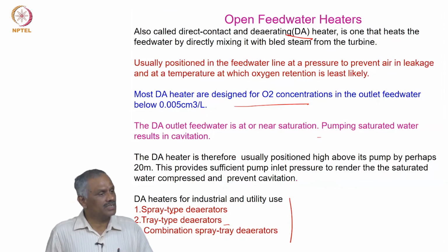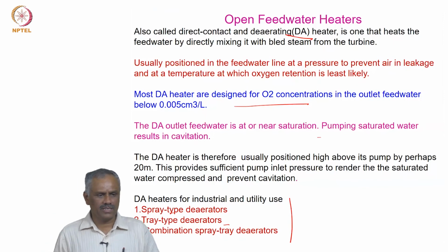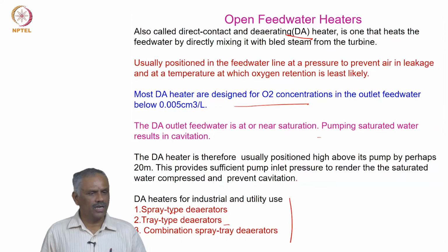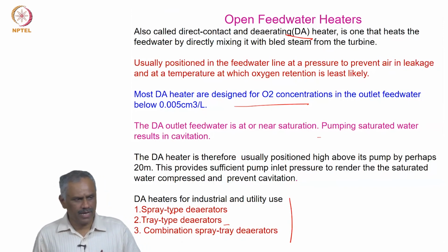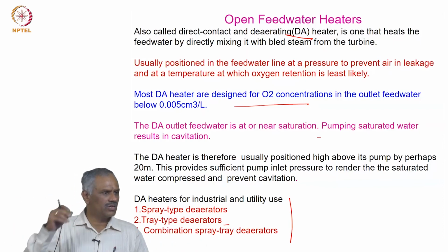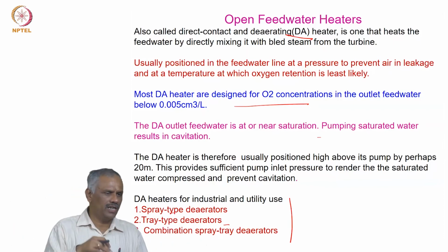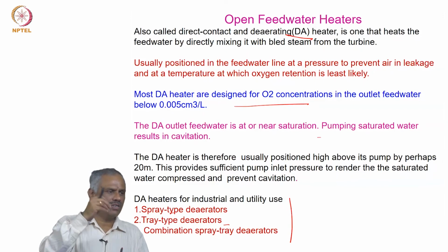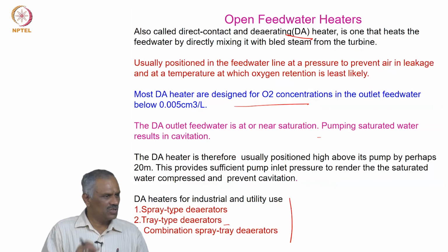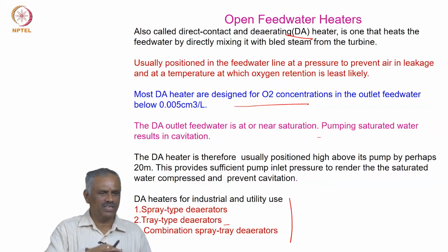But how do you generate suction? Every time you have to create suction. Suction can be a batch process or a continuous process. Essentially, it is a batch. Suppose if this room is there, you have to create suction in order to condense, but then after condensing some mass, the suction will become positive. So, therefore, you have to continuously create low pressure in this.